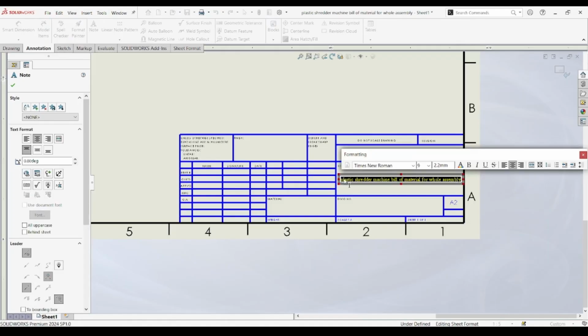We also dive deeper into how SolidWorks drawing features complement the BOM creation process. Specifically, we cover how to generate detailed 2D drawing sheets directly from the 3D assembly. This includes setting up standard views like front, top, isometric, and section views to visually communicate part geometry. Once the BOM is placed on the drawing sheet, you can easily create exploded views with automatic balloon annotations.